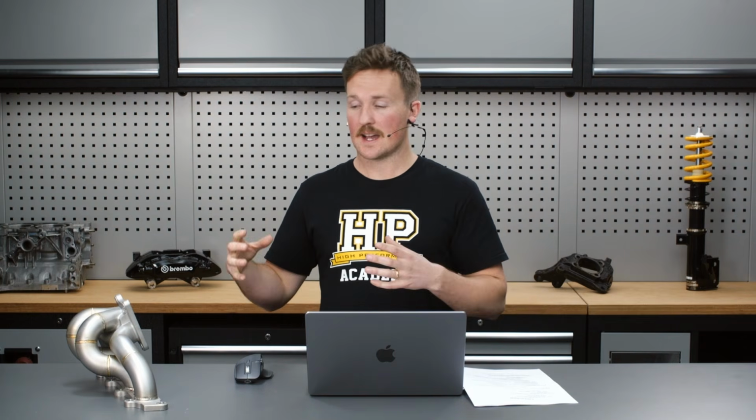So the thing with 3D scanners is they create a mesh file. If you're watching the pre-show, we did a quick scan, it captured the data as a point cloud, and then I process that and it turns it into a mesh file, and then we bring that into our CAD software. Essentially, a mesh file is the outside surface of the model broken down into usually hundreds of thousands, if not more, of tiny little elements.